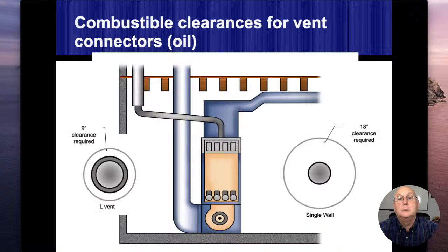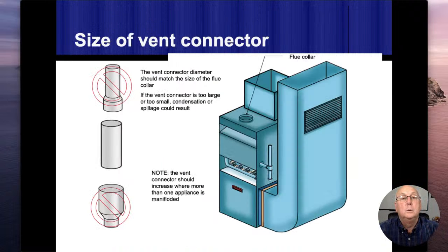Oil connectors. This drawing is saying 18 inches. That's an apology from me, all right? Those numbers that are written on there are incorrect. Oil is going to be 9 inches. Wood will be 18 inches. And an L vent is actually also 1 inch. We're going to get off that slide real quick so there's no proof of my mistake.